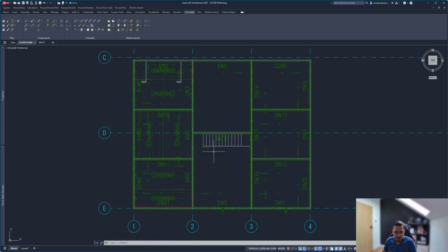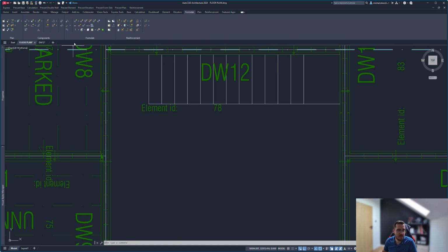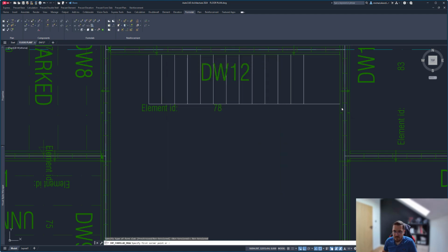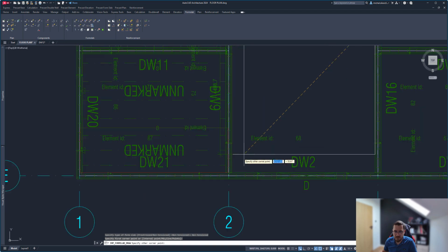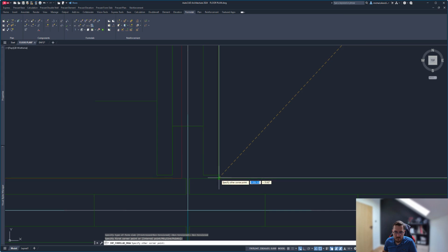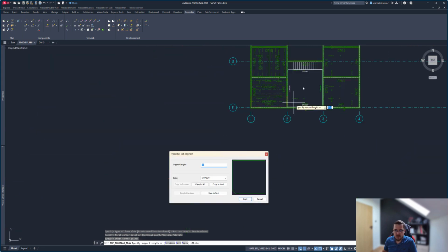And with this done, let me go ahead and actually add the last set of slabs here, just so you can see how fast it is and how easy it is. Yeah, same type of slab, except what I'm going to do, I'm going to click through here and change that to here. And I'm going to make that an 80. Skip to next. This one is going to be 0. Step to next. It's going to be an 80. And next and 0. So that's just basically the end cap as well.